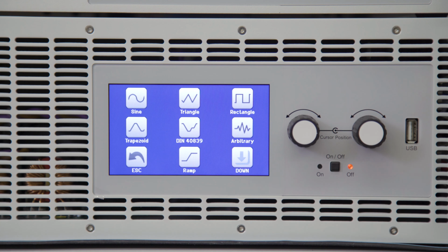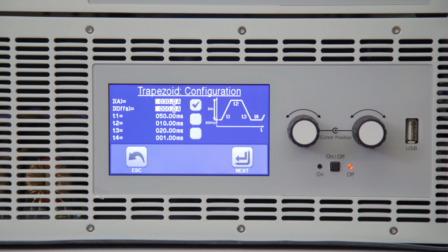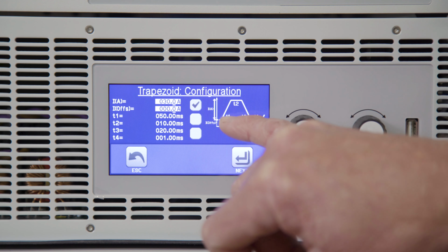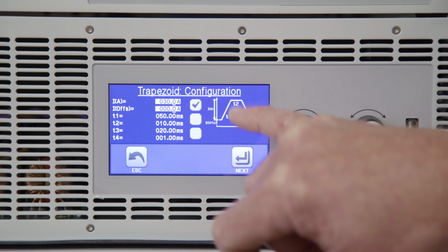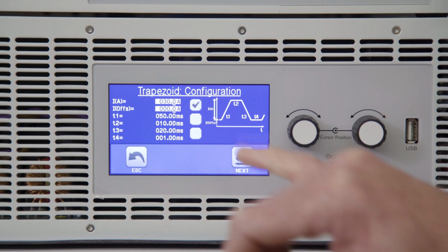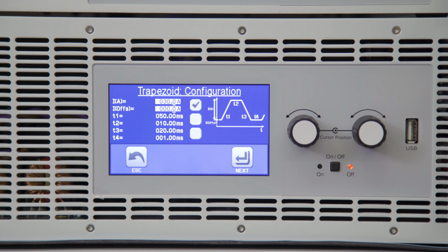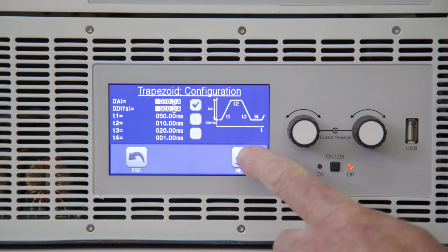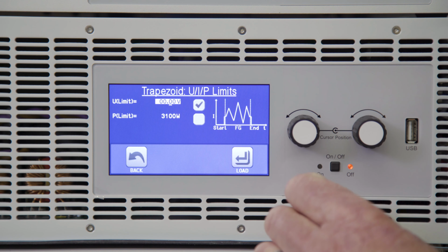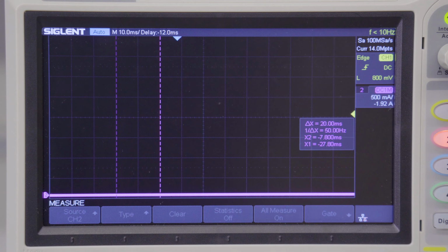Now we'll take a look at trapezoid. What I've programmed here is a current going from 0 amps to 30 amps over a period of 50 milliseconds, staying there for 10 milliseconds, ramping down T3 at 20 milliseconds, staying there for 1 millisecond, and then repeating that sequence. We'll load it in. Of course, you have your safety features as well. We'll load it and start it.